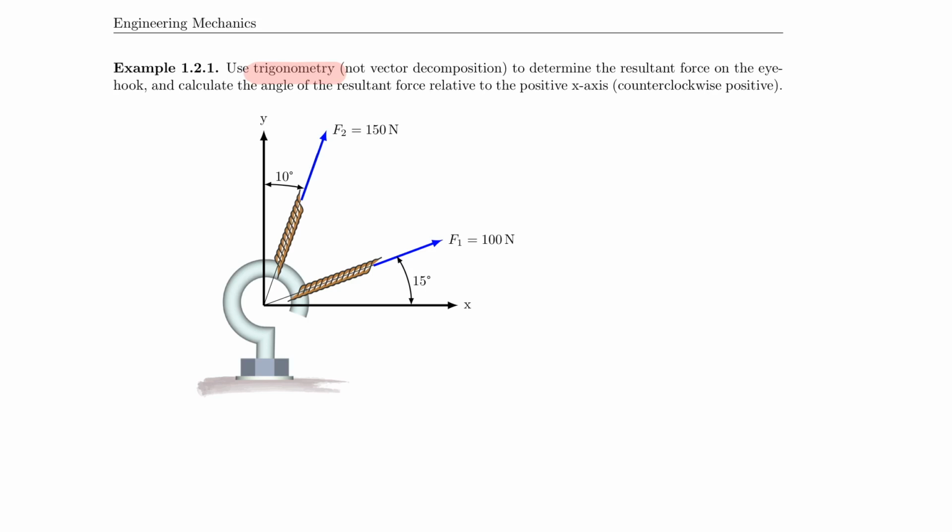So let's do that. I first will move my F1 parallel along this line, and then I will move my F2 parallel along this line here. And now the diagonal within that trapezoid is really my resultant force. So let me put that in for you. So this would be the resultant force, or this would be the visualization of it. So F resultant is what I call that.